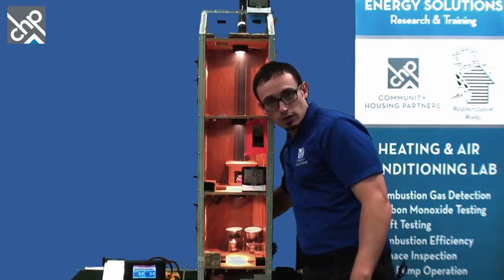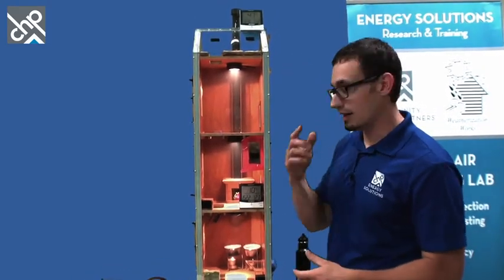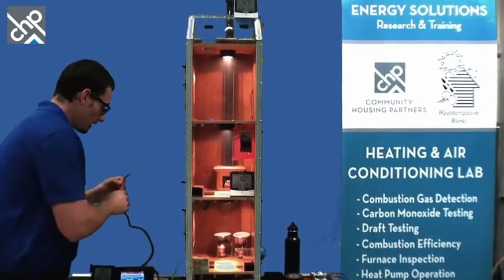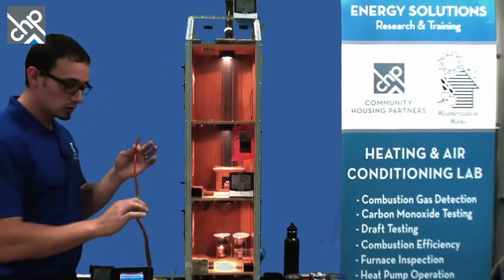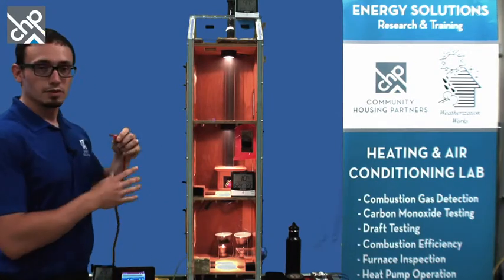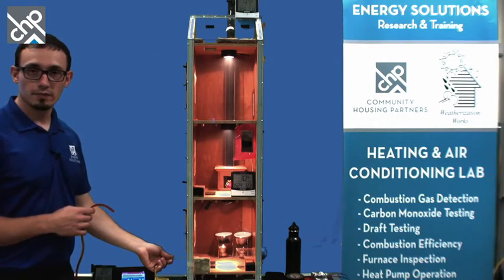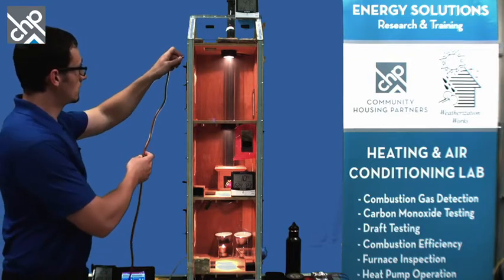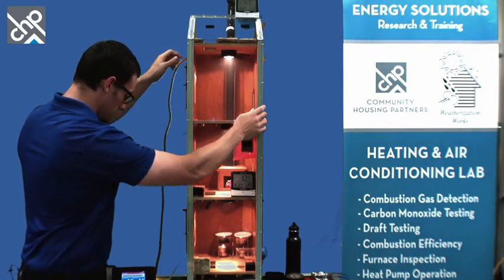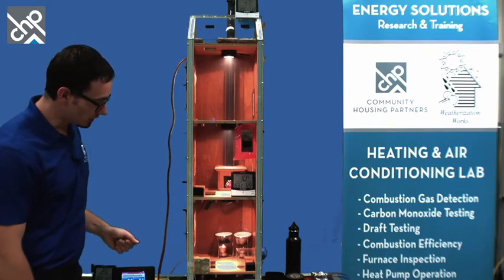Now what we're going to do is explore a little bit via the manometer. We're going to actually measure the pressures inside of the house. So I'm going to switch over here. I've got a couple of pressure probes hooked up to a DG-1000 and a couple of manometer hoses here. I'm going to place one of these at the top of the building, and the other down at the bottom of the building. What that's going to tell me is the pressure on channel A, the red hose, is going to be the pressure at the top of the building. The hose down here is going to tell me the pressure at the bottom of the building.